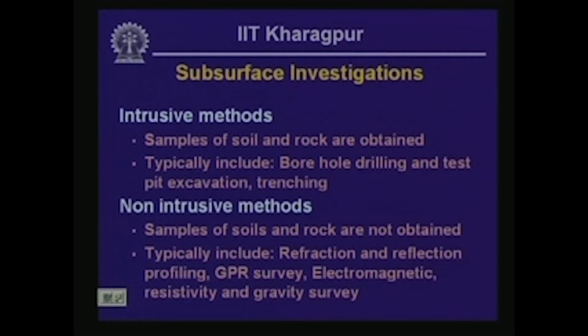These subsurface investigations can include intrusive methods in which a borehole is drilled through the different geologic units, or it could include test pit excavation and trenching, and by looking at the different features on the walls of the test pit and trenches one could correlate different geologic units.